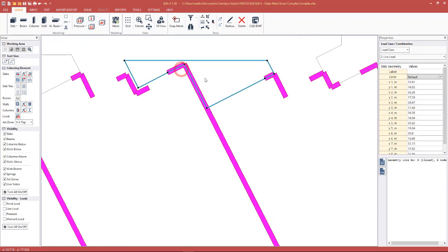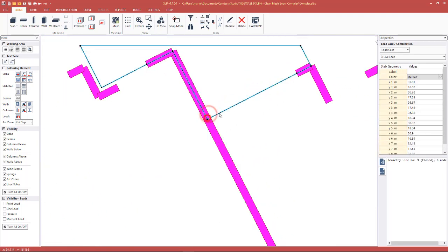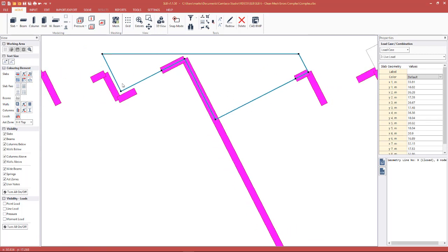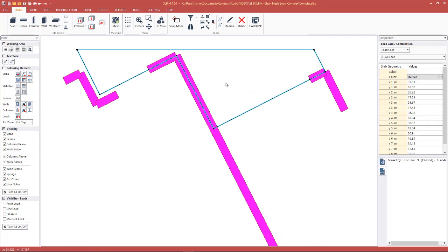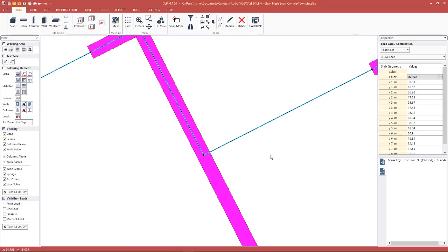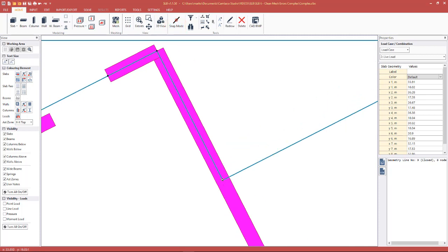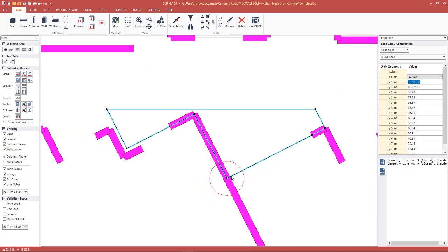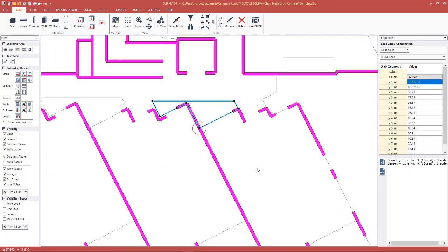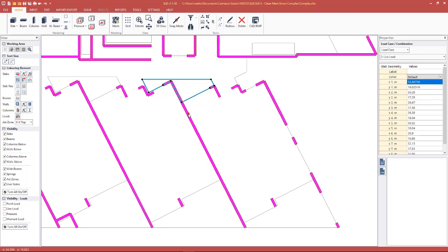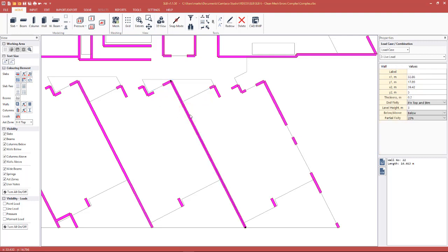And we repeat the exact same process here. Now, because this geometry line wasn't exploded in the various automatic operations we did, rather than extending and clipping, we can simply change the snap settings to snap to edge. So we just drag it across, drop it down, and basically that's the level of accuracy it needs to snap to that wall end. So this should fix all of the errors along this wall's length.